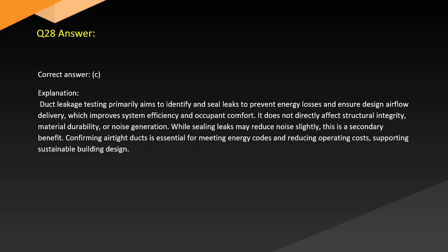Answer. Correct answer, C. Explanation. Duct leakage testing primarily aims to identify and seal leaks to prevent energy losses and ensure design airflow delivery, which improves system efficiency and occupant comfort. It does not directly affect structural integrity, material durability, or noise generation. While sealing leaks may reduce noise slightly, this is a secondary benefit. Confirming airtight ducts is essential for meeting energy codes and reducing operating costs, supporting sustainable building design.